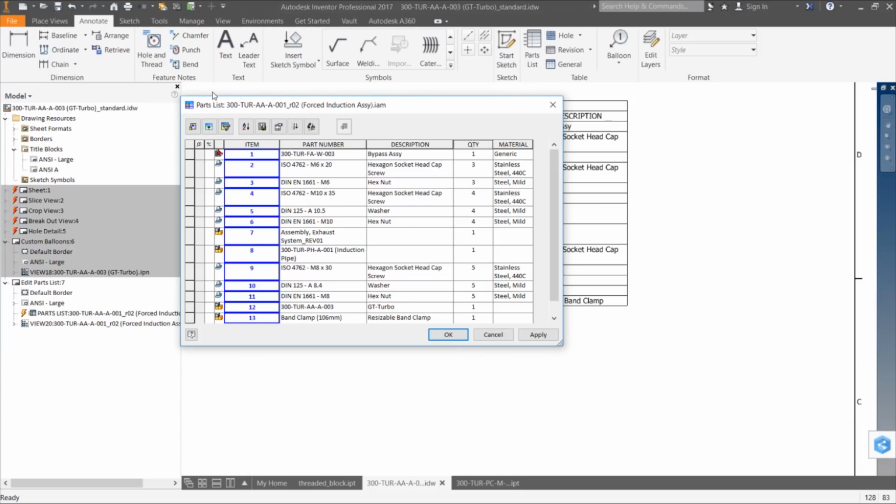And actually, Nigel, you bring up a great point. I have a lot of customers that use Frame Generator to develop parts, and what they're after is how many 10-foot pieces of steel do I need? By default, the parts list doesn't tell you that. There's a very simple, very easy workflow that does that. So if that's something that anyone on today's session is interested in, we can put together a short 5-minute video that shows you how to reconfigure your parts list to give you quantity and cut lengths. Yep, I know that's a big deal for a lot of our Frame Generator customers for sure.